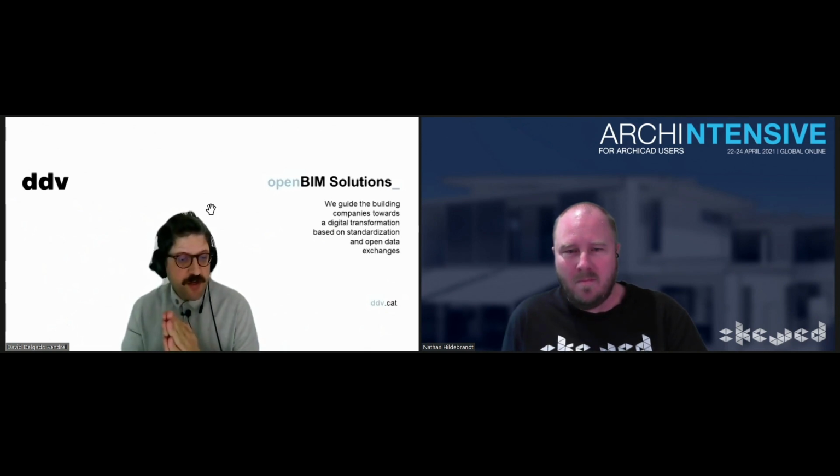So then we need to elaborate a workflow. In this case, it's the workflow that we have found using the tools that we are familiar with, which are CloudCompare, Rhinoceros, and Grasshopper. We are using some plugins with Grasshopper, and there are dozens of them. This is a quite active community providing stuff for point clouds.